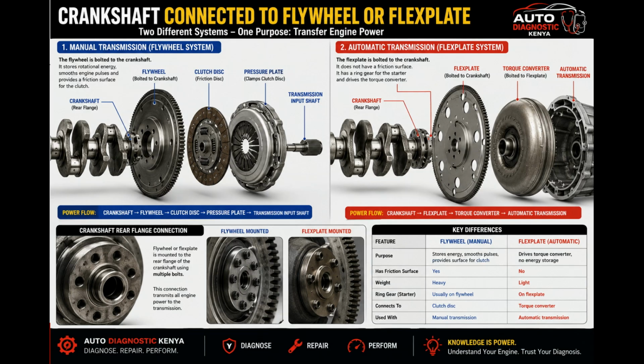Why? Because the crankshaft and the flywheel are balanced. They are balanced separately, but they are also balanced as an assembly. If you change the relationship between them, you can create imbalance, and imbalance means vibration. Imagine the crankshaft has a small amount of imbalance. The flywheel also has a small amount.